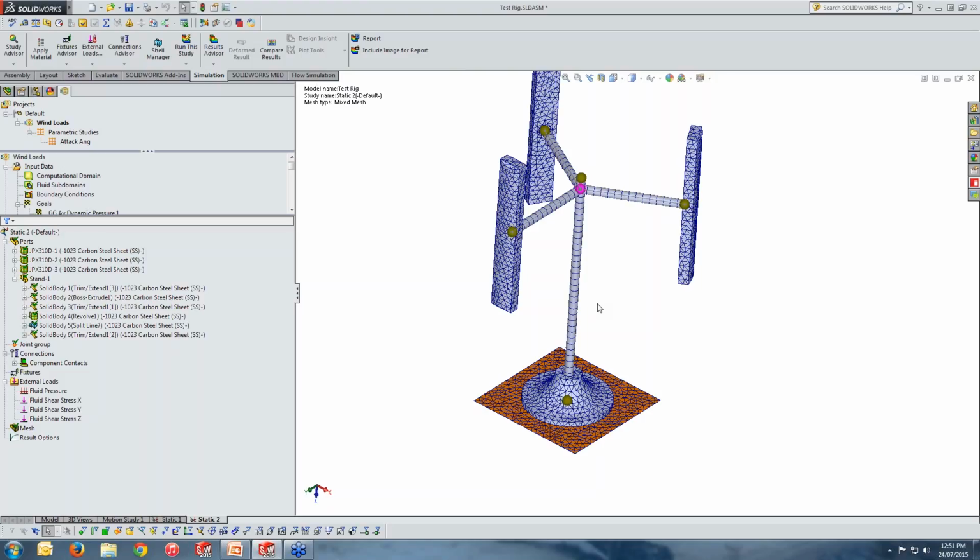Therefore, when you have a solid attaching to a shell, you might create a hinge connection, since you might simply bond these two components with their translational degrees of freedom, but since the shell or the beam has 3 more to be bonded, they might create a hinge connection.